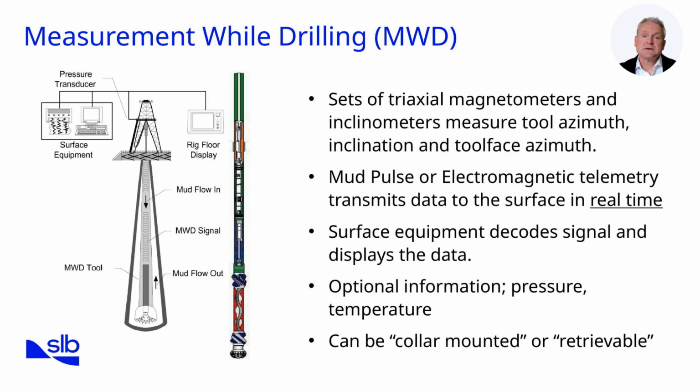Limitations include dependence on mud properties for mud pulse systems, limited bandwidth, typically less than 12 bits per second, and susceptibility to magnetic interference. Nonetheless, MWD has become the industry standard for directional drilling, rendering older systems, such as single shots and steering tools, largely obsolete. Its introduction transformed drilling from an episodic survey check approach to a real-time navigation process, enabling the complex well profiles we now take for granted.